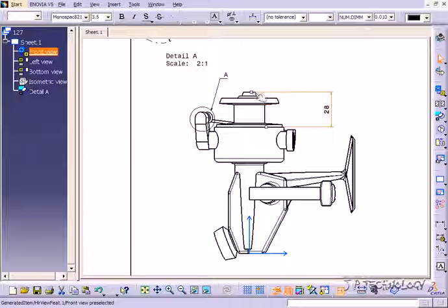Now if you click on here, you're also able to pull this back to pull the lines back. Now when you're doing dimensions, you want to make it as close as you can without touching. So keep a little bit of a gap there. In this case, it's a little bit off because I didn't touch this line, I used this line. So let's just delete this and we'll do another one.